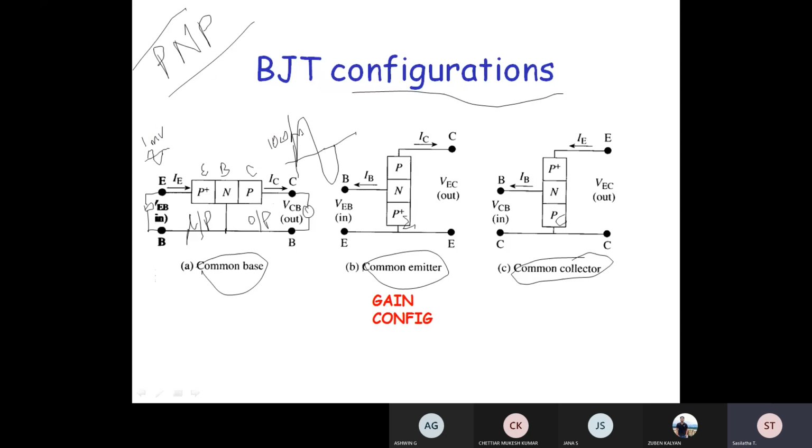Depending upon the parameters, what is being used, resistors, whatever may be connected over here. Let me say that this is the input signal and this is the output signal. After amplification, the transistor is acting as an amplifier. It has very good gain. Gain means what? Output voltage divided by the input voltage.